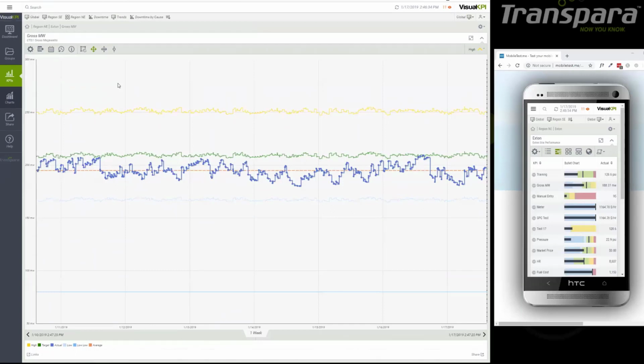The second is a managed trend. That means the administrator made it up. It might have 3 or 4 different things going on, or 20 different things going on the trend, and it was sort of custom made and available to everybody. The last one is the ad hoc trend, which we already covered a bit. You can make one from scratch, or you can take an existing trend and add additional pens to it or take them away. Okay, so I'm looking at a KPI trend.